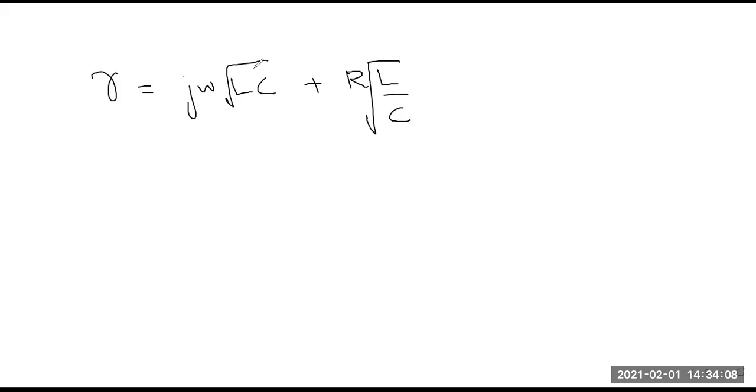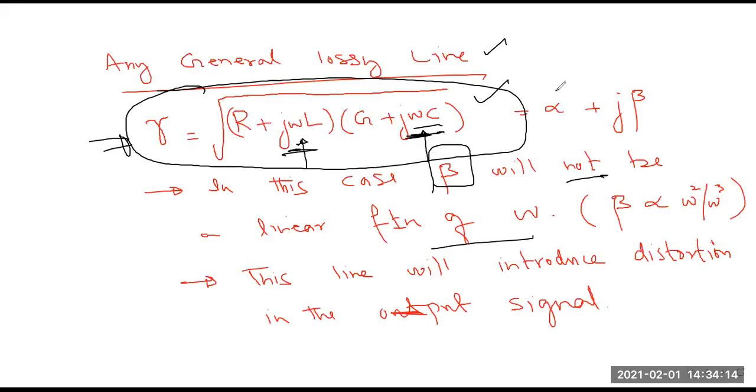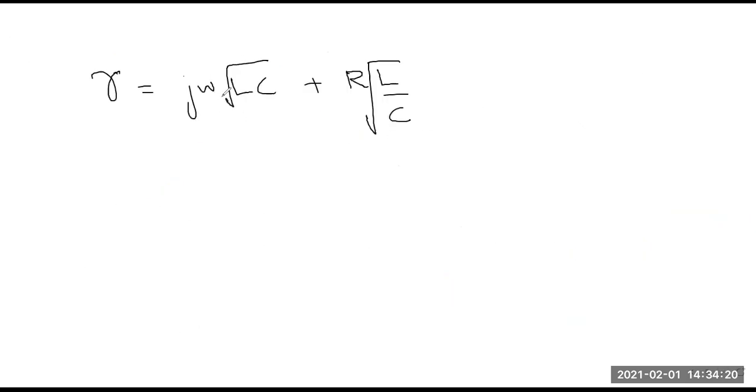So now you can clearly see this is propagation constant. And we mentioned that this propagation constant has a real part and imaginary part. And based on this simplification, what we know, this thing, j times this thing, this is beta. So this something is beta. And this is a real number, so it must be alpha.